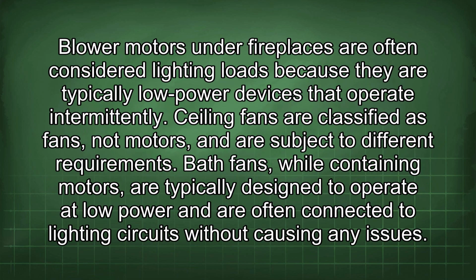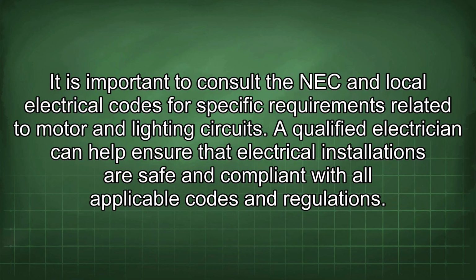Blower motors under fireplaces are often considered lighting loads because they are typically low-power devices that operate intermittently. Ceiling fans are classified as fans, not motors, and are subject to different requirements. Bath fans, while containing motors, are typically designed to operate at low power and are often connected to lighting circuits without causing any issues. It is important to consult the NEC and local electrical codes for specific requirements related to